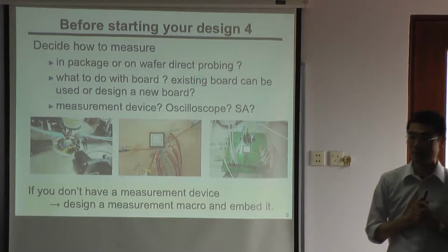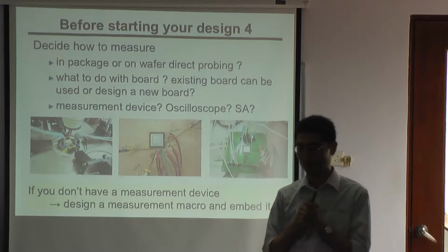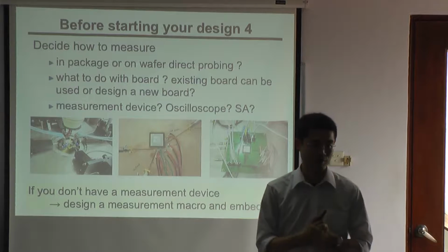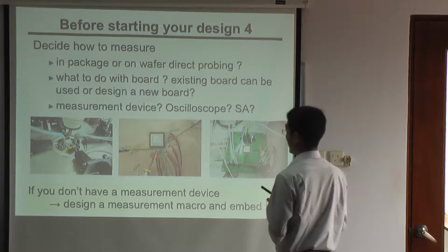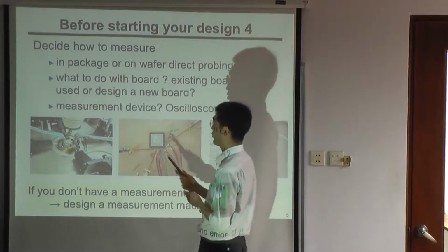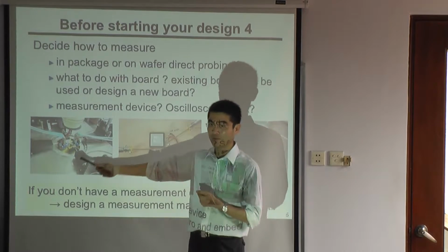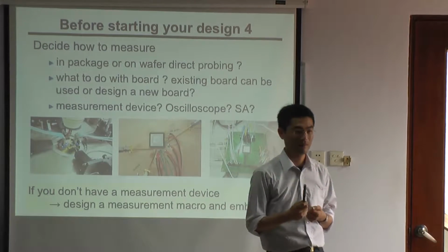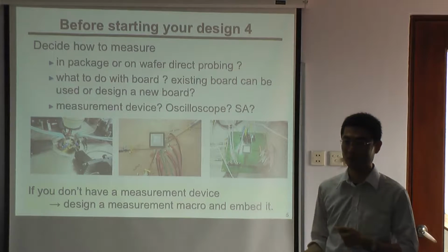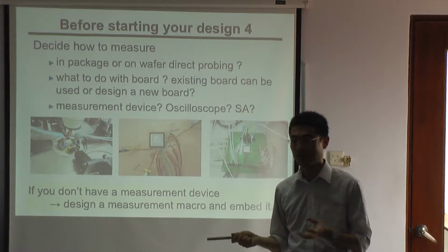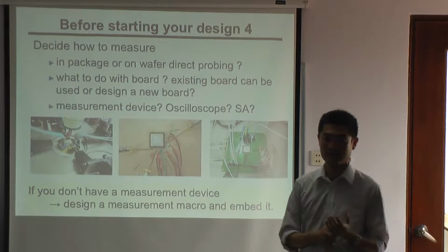And also, before starting the design, you have to consider how to measure your chip. You will measure it in a package or on wafer. You have to consider it, and based on how you measure, you will decide what kind of circuit you want to design.